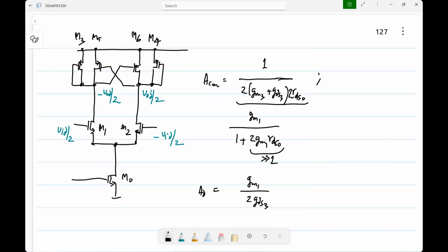That means you should have common mode rejection somewhere. If you don't have common mode rejection anywhere, then this business of using two wires for each signal may or may not make any difference. The idea is that finally you are sensing the difference voltage between the two wires. That's another way of saying you have common mode rejection, because you're only sensitive to the differential signal and not the individual signals.